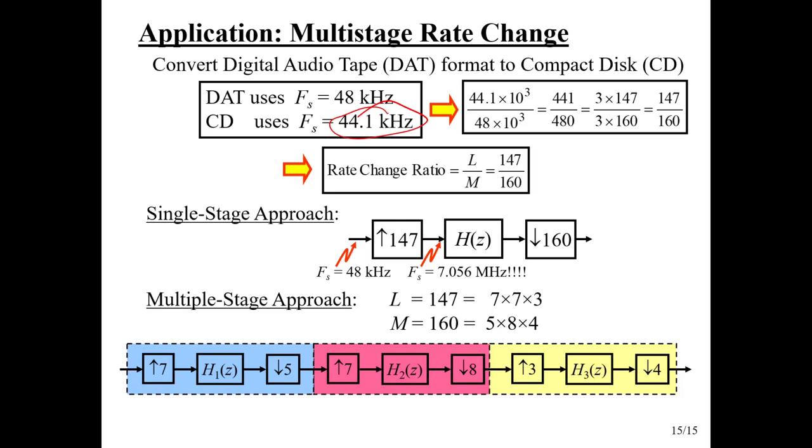So you want to pick those so that you get the best efficiency, and also likely that would hinge on making sure that the intermediate sampling rate anywhere in the system, first of all, never drops below 44.1, but then the largest sampling rate that you'd have anywhere, you'd want to pick the order to make that largest internal sampling rate the smallest of all possible choices.